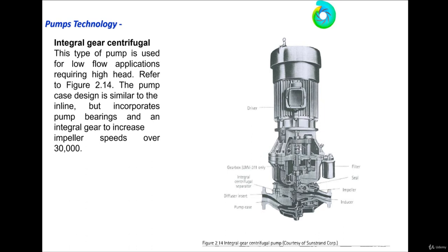That means you need 1, 2, 3 cubic meters, up to 10 cubic meters per hour. At the same time, you have a high pressure, meaning 300, 400 meters, 30 bar, 40 bar. Within this flow and pressure range, the overhang pump cannot handle it. And the solution is either to go to a positive displacement pump, or you can order this pump.